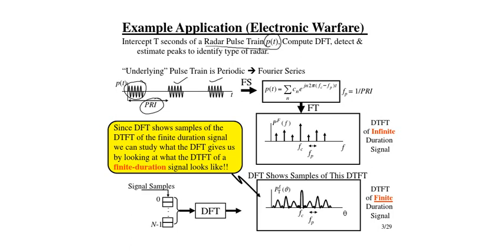When we write the Fourier series expansion for PT, it can be written as the sum of Cn times e to the power j 2 pi (fc minus n fp) t, where Cn are the Fourier series coefficients, and this is your Fourier series kernel, which is at fc and shifted by fp, where fp is the inverse of the PRI. So what essentially happens in the spectrum domain?